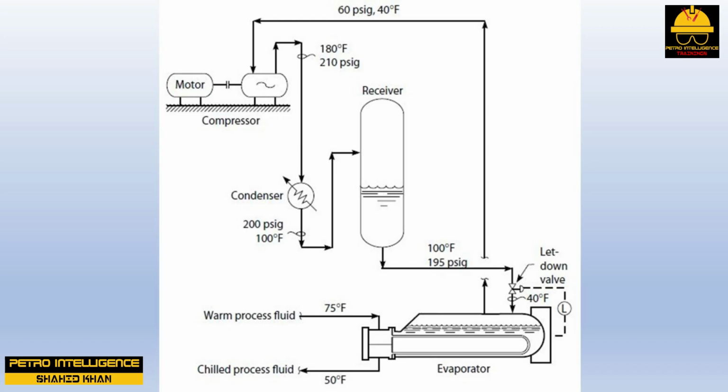The reduction in the refrigerant vapor flow reduces the workload on the compressor. But the reduction in the suction pressure increases the compression ratio, discharge pressure divided by suction pressure. This increases the workload on the compressor. As we have discussed in our lecture on centrifugal compressors and surge, increasing the compression ratio is a small effect on compressor workload as compared to decreasing the vapor flow, as long as we are operating on the flat part of the compressor's flow versus head performance curve, which is almost always the case for a centrifugal machine.